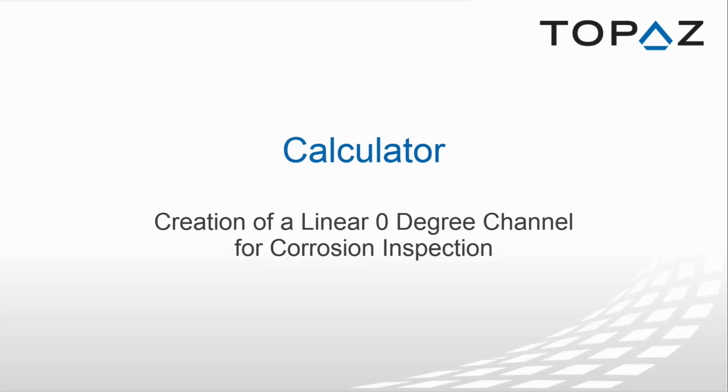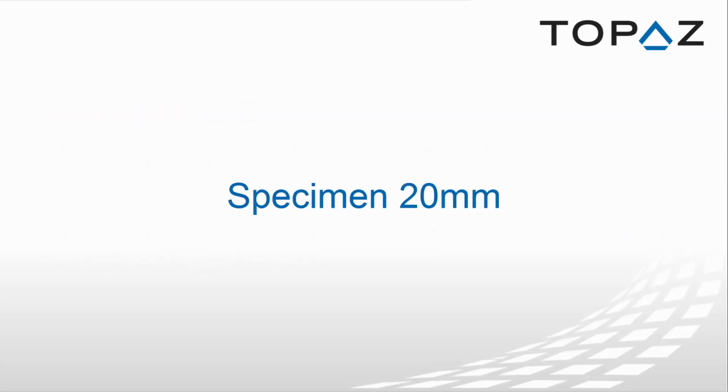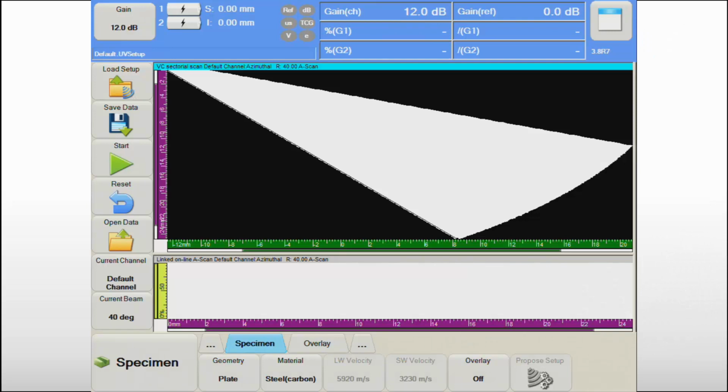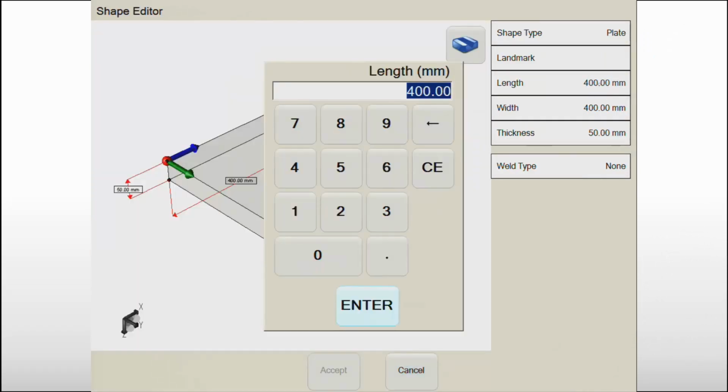Calculator, creation of a linear 0-degree channel for corrosion inspection. The specimen. The first step into creating a setup is defining your specimen. It will help you create your UT configuration and also help you with data positioning. We will begin by looking at a specimen at 20 millimeters. We will create a UT phased array configuration for the following specimen.